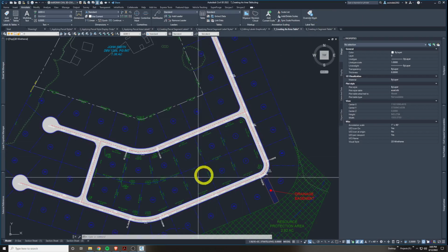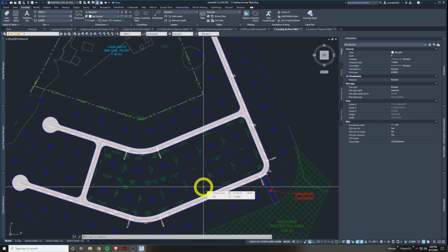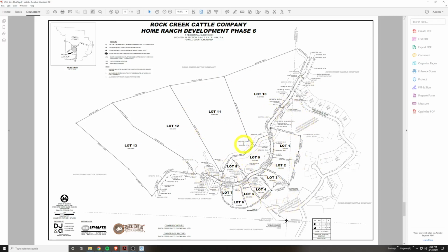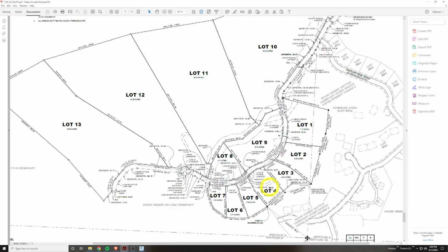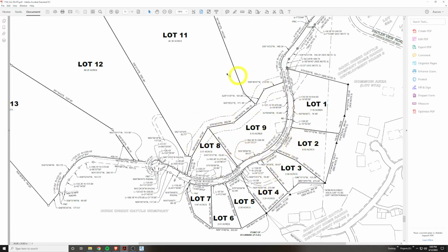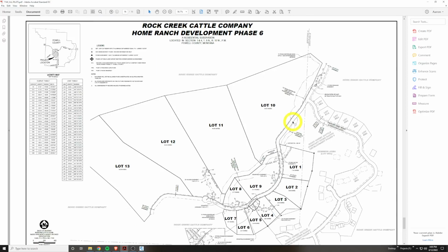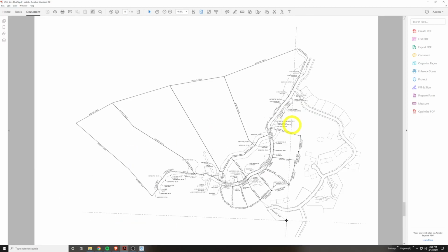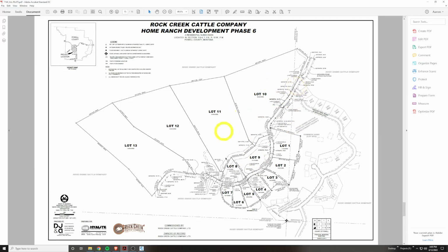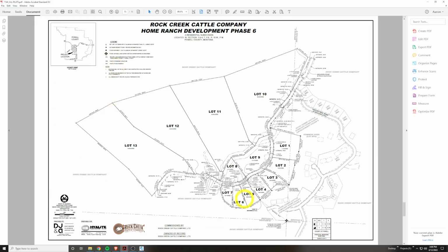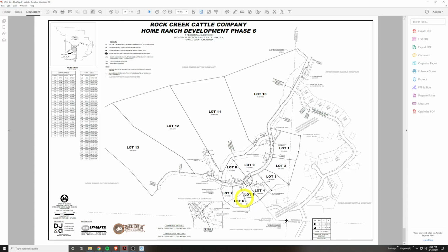Excuse me. And oftentimes the tables can have unique tags. For example, if I go to a different project here, you can see an exact same area of the subdivision I did in Montana with all the parcel segments and lines and curves labeled, and it got really tight. But I still needed to label all these little easements and various things legally on this subdivision. So I go to the next sheet, literally a mirror image of itself, but different labels. So this one has all of them fully graphically shown. This one, I have tables for all my curves and for my lines. And you can see the difference. See how much more cleaned up one is?